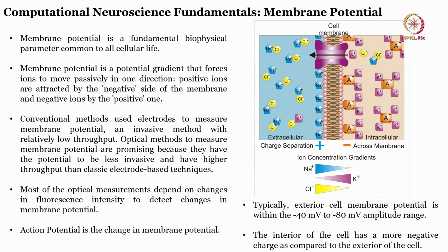Now, in terms of designing an electrode or a system, electrical systems, for example, where you measure the impedance or the resistance or the capacitance, are very easy to develop. Optical technologies are comparatively complex to develop. But the optical technique has several advantages: it can be used in a non-invasive way, and it is much more accurate. So depending on what kind of application, you can either go for the electrical parameter or the optical parameter.